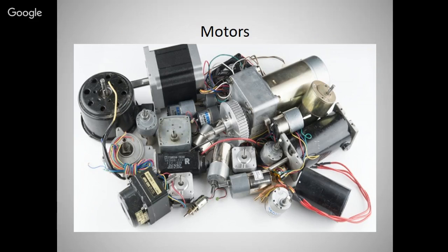Now motors. You can see the motors I have used here: a DC motor, 12.5 rpm, 24 volt, and 200 milliampere rating. You can write this down if you are interested, because if you want to make this project, then this specification is important. And we can communicate about this. If you want, you can get any information.